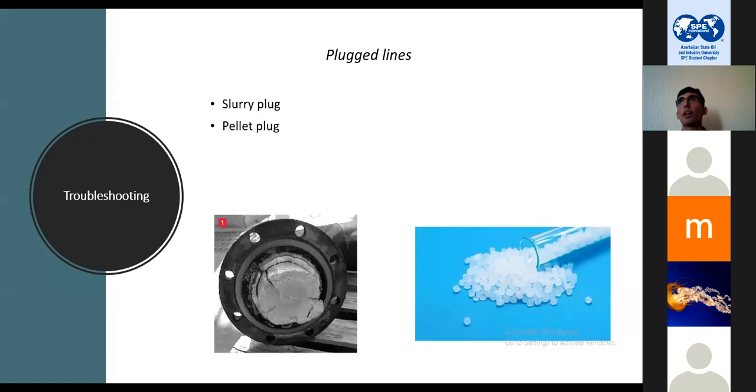So some interlocks have problems discharging the reactors. Some valves will stay closed, and at that valve the slurry cannot go out, so it stays there. As time goes on and the temperature goes down, it turns into solid form.